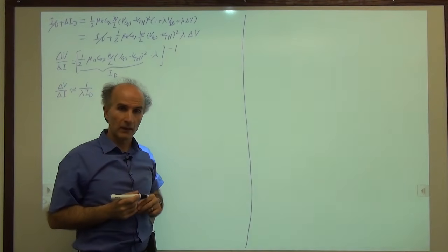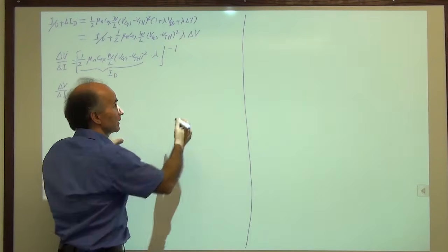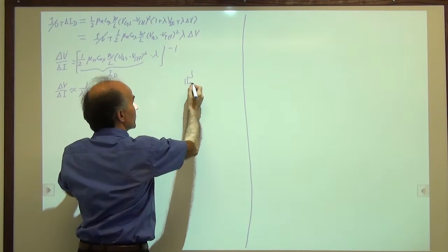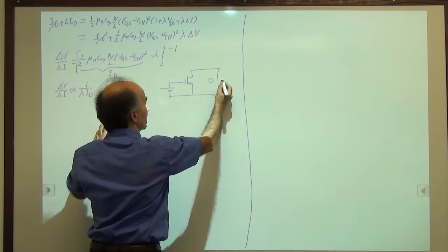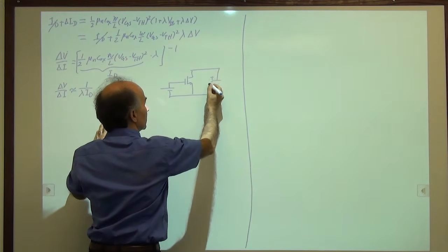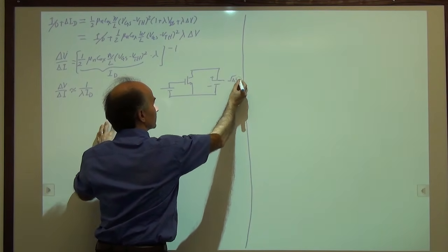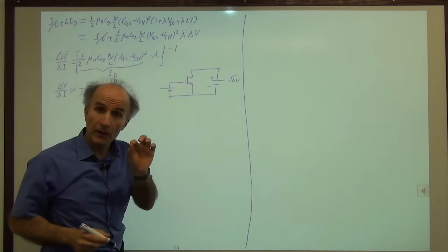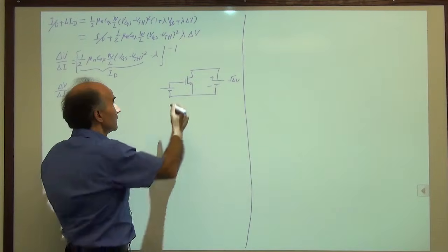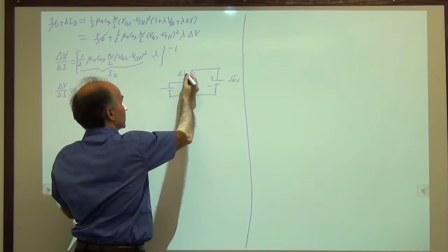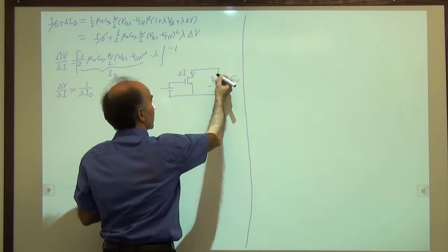All right. Okay. Now, what does this mean anyway? Well, we have a special case here that allows us to not use a voltage-dependent current source. So here's what we've done. We incremented this voltage source by some amount, delta V, right? And in response to that, we saw that the drain current changed by delta I. This current changed by delta I. But it just happens that that delta I is flowing out of this battery here, right?